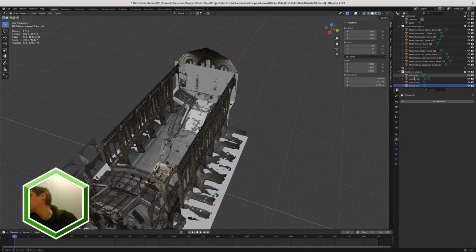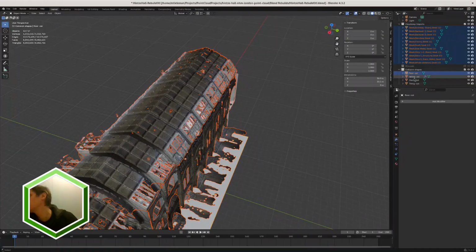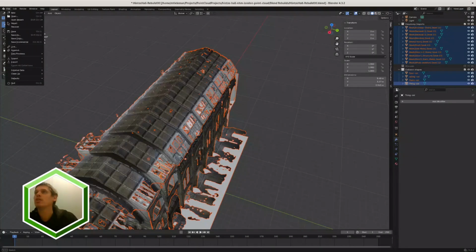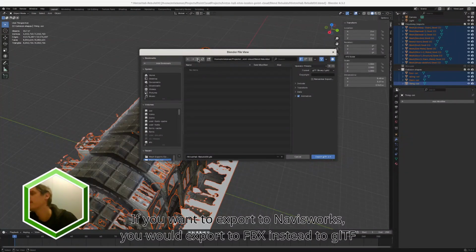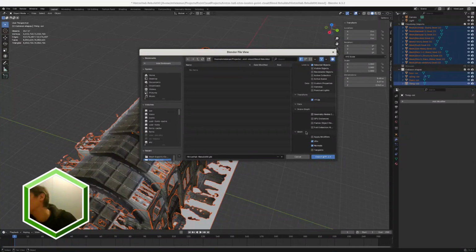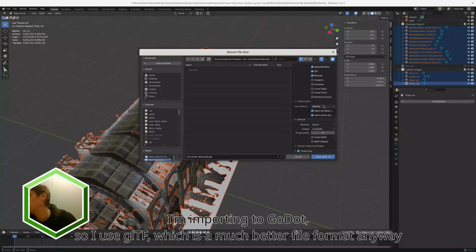So what we're going to do now is select everything here. Select this, this. Put the file, export, glTF 2. Just put it here, why not? A couple of things to keep in mind. We don't have any animation, so I'm going to disable that. Y is up. Only make it selected objects. Yes, apply modifiers. In this case, yes. Sometimes you don't want to do that, but usually it's better to do that. Pick active for